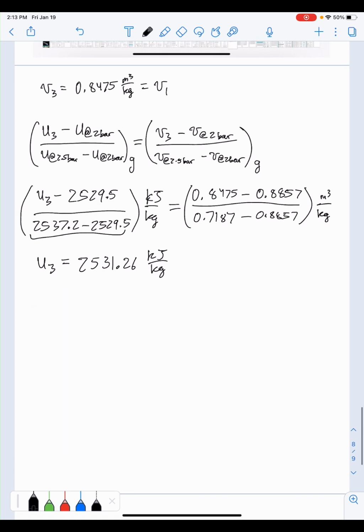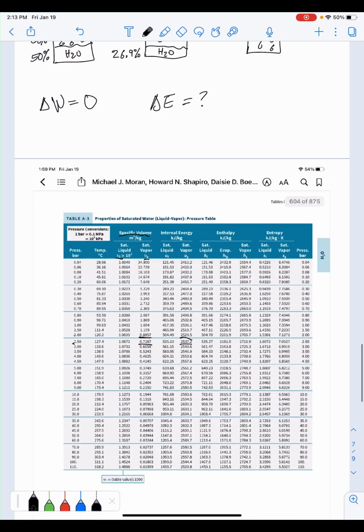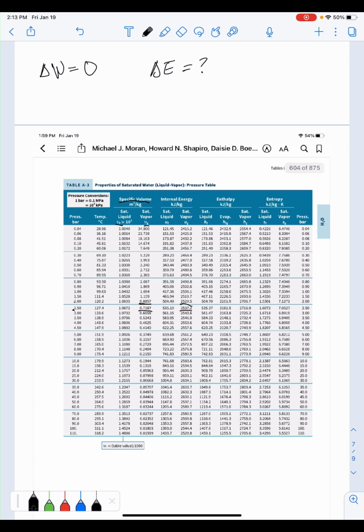Okay. So the process to find the internal energy at state 1 is actually easier than I remembered. The process is to go back to the steam table. So earlier we interpolated because we knew that our specific volume value lay between these 2 points, but we didn't exactly have it, right?